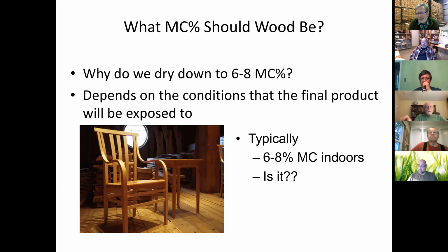And typically an interior environment that's heated with heating and cooled with air conditioning is going to be a pretty close average if we look at the moisture content throughout the year for the average of the United States. Now notice I keep saying the average, because in my opinion, the conditions that you want the final product to be exposed to are what you want for the moisture content of your wood, whether it's in your shop, in storage, or going somewhere. For the life of the product, it should be based on the area that it's going to.